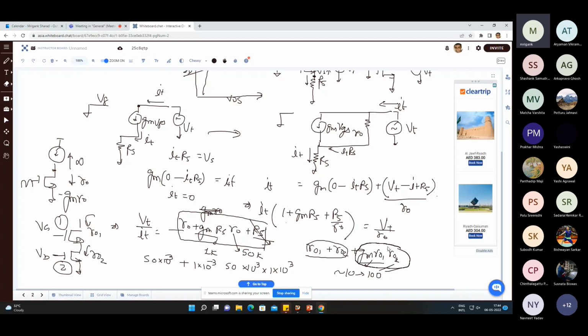So generally in design considerations, we rely on this product term because in most cases this will be the dominant term, and we can ignore the other two terms. And if we have a condition like this, definitely we can see that the output impedance will be very high. If you were looking into only the drain of an isolated MOSFET, the impedance was RO, but now it is GM RO times RO. So basically the gain is getting multiplied by the intrinsic gain of the MOSFET.